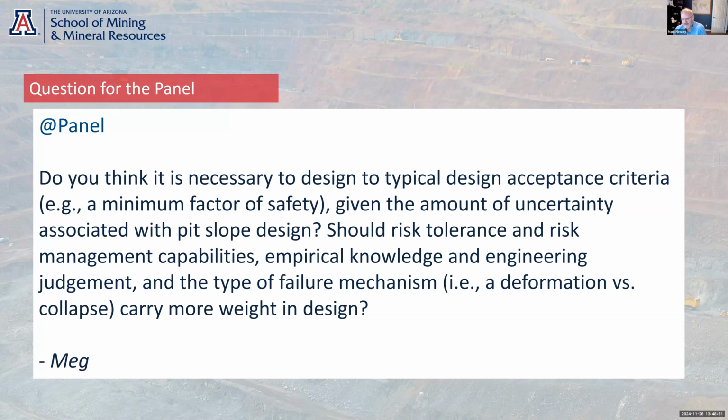And it has to be a continuous feedback on that. I don't really put too much focus on factor of safety once I'm into an operating slope. I think it's more about, is the slope safe? Are we managing the rockfall rate? Are there deformations that we can explain that make sense in terms of the mechanism that we think is controlling the interramp and global stability? Those are questions that are always going on, and you're always adjusting your thinking based on the latest monitoring data or the history of the monitoring data.